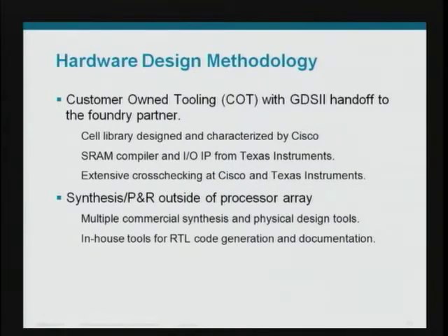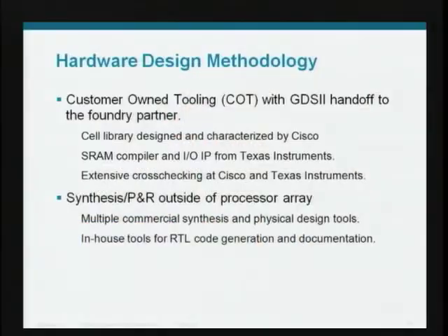And you never turn down verification, right? This was additional verification that a parallel team did, and it turned out to be very, very beneficial to us. Outside the processor array, it was synthesis, place, and route, multiple commercial synthesis tools, and quite a bit of in-house RTL code generation to do that.